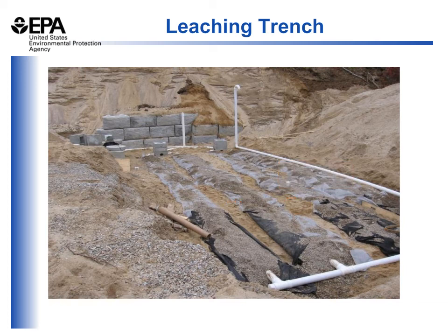Each trench is built with a PVC pipe that's perforated, so the effluent leaving the distribution box flows into the trench and exits through the holes in the perforated pipe. The pipe is surrounded by washed gravel that's very permeable, and if a larger flow of effluent is coming in, it can actually be stored in the pore spaces around the gravel while it seeps into the ground below.